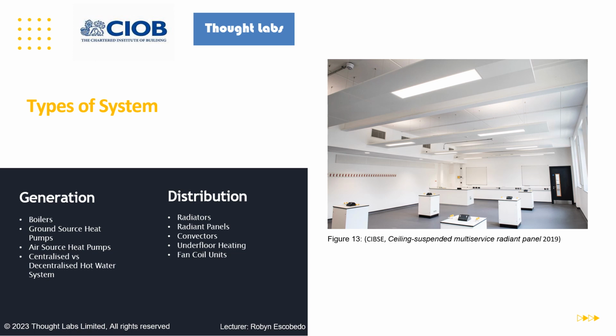However, they will need to be coordinated with the lighting design. For example, if radiant panels weren't an integral panel with the lighting in this installation, then the electrical engineer and the mechanical engineer would have to converse with each other to make sure that there are no clashes between their proposed designs. Occupants may also report hot head, cold feet syndrome if the panel is heating their head first if they're too close to the panel. Therefore, the siting of these needs to be carefully designed.